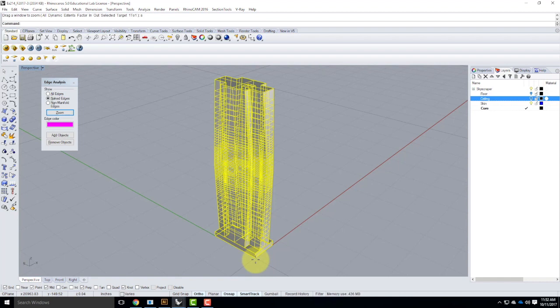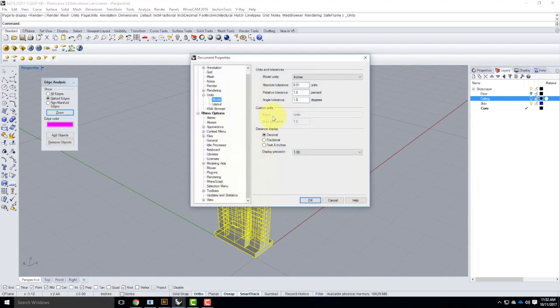Oh, it looks like I'm doing this slightly out of order. We can do the mesh first. It doesn't really matter whether I switch the units or not. But in this case, since I'm already on this track, I want to switch the units. I'll go to where it says inches down here on the right. We've done this before. I'll right-click on it, and I'll say Unit Settings. And I'm going to switch the model units from inches to millimeters.